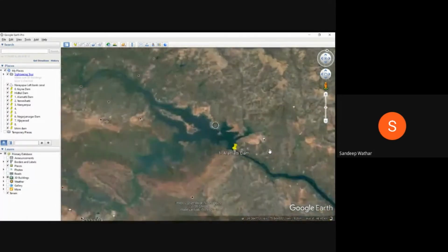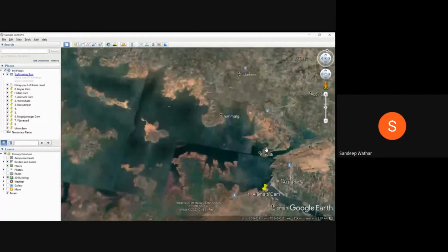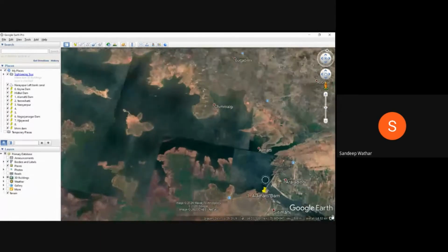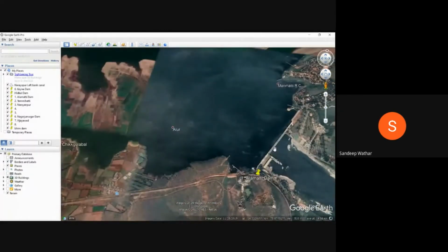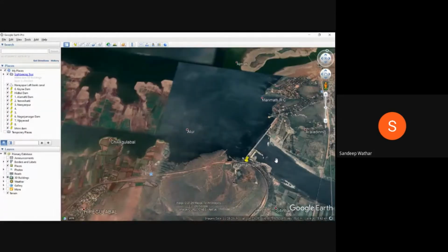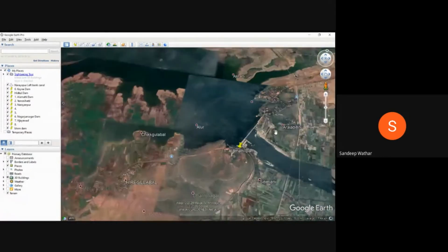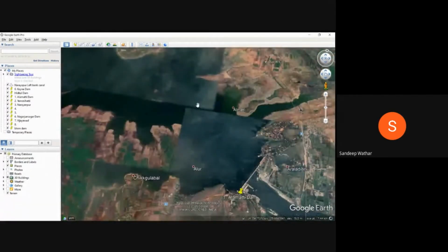Okay. So whenever the water comes, it carries a lot of soil. The soil gets settled at the bottom of the dam, somewhere here. This region basically gets silted up because we are storing the water. The water is also carrying suspended solids. So all those suspended solids will get settled in the dam area itself, on this upstream side itself.